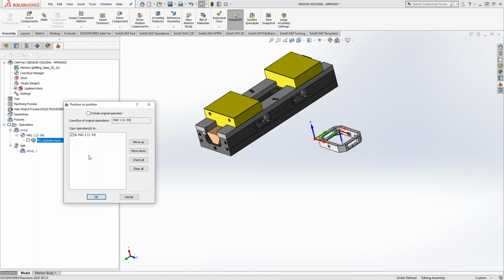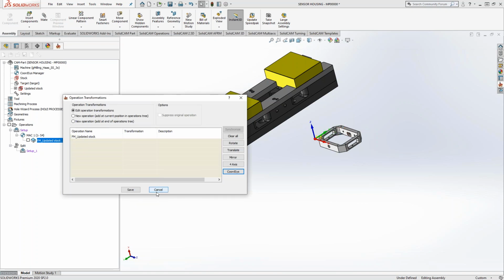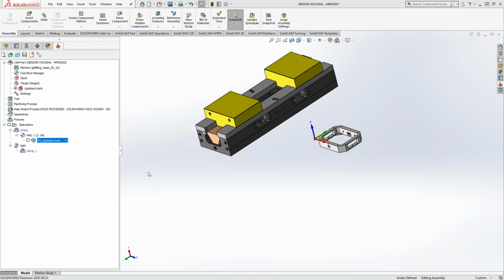And those coordinate systems don't have to be in line with anything at all. So when Mark showed the transform of those coordinate systems, they could be off in la-la land. It really doesn't matter, because when you go to run this on your machine, you're finding your G54, G55, and G56. Exactly. You can do it visually inside the software, but on the machine, you're actually setting up those individual offsets. So, Pierce, does that answer your question?